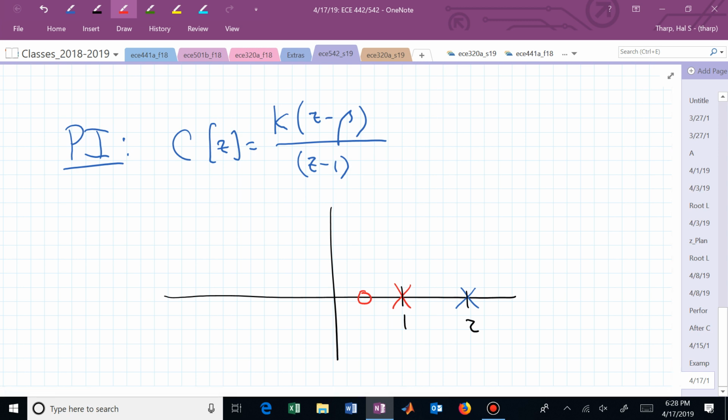Why? It's outside the unit circle, and we never, ever, ever want to cancel poles and zeros outside the unit circle. That was Ragazzini. Ragazzini gave us those rules that said, make sure that this 0 factor is in your closed loop transfer function so that we don't cancel an unstable 0.